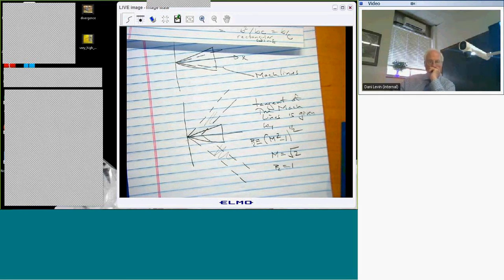If you're careful, it depends on which code you have. I think if you put in the right reduced frequency, make it high enough, and set the Mach number equal to 1, you'll actually get an answer. It won't blow up. Whether it's a good answer is another question. They have a specific model for Mach 1? Yeah, they do. That's right.